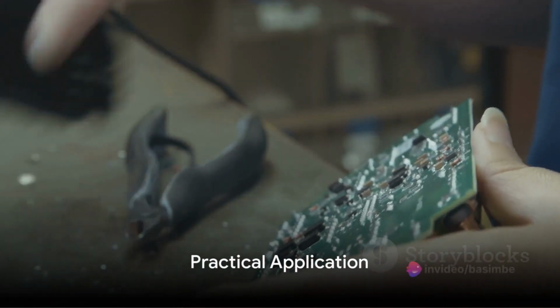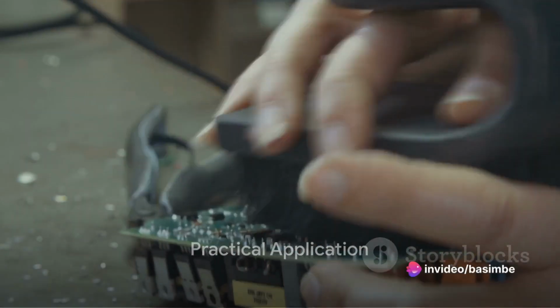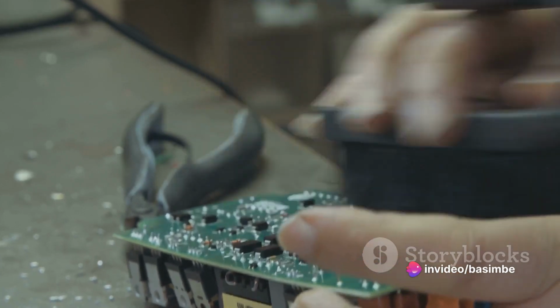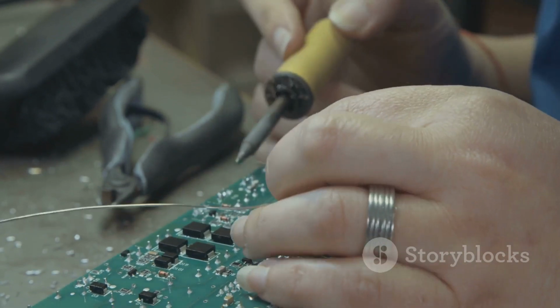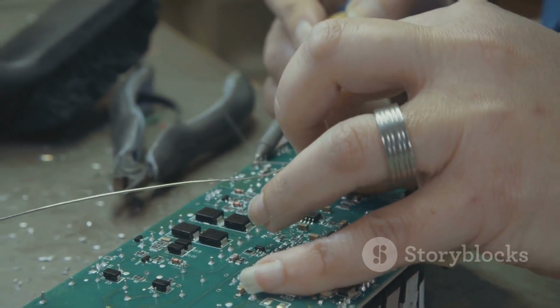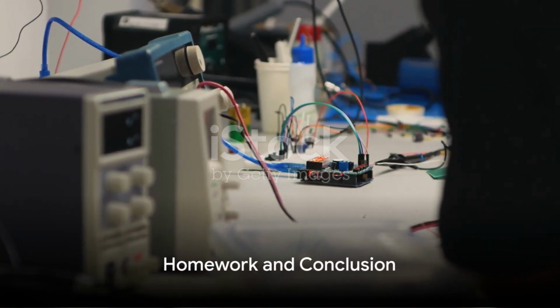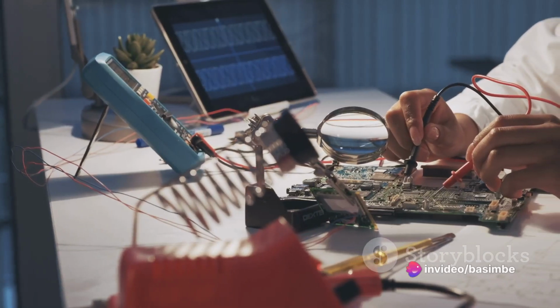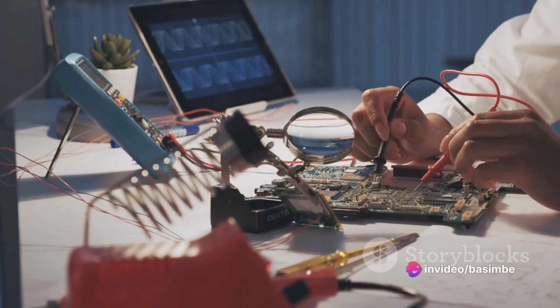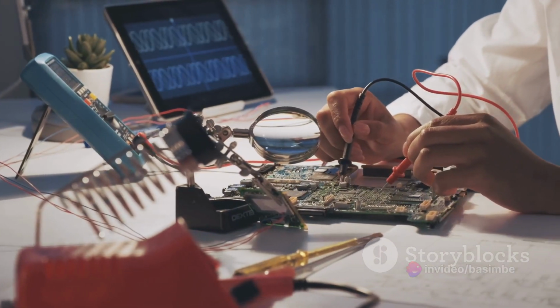Now let's see how you can practically apply these concepts. Try building a circuit with a power source, a resistor, and a load, such as an LED. Experiment with different resistor values to regulate the voltage across the load. For homework, practice analyzing series and parallel circuits using Ohm's law and Kirchhoff's laws. Also, explore more about multimeters and how to use them effectively.